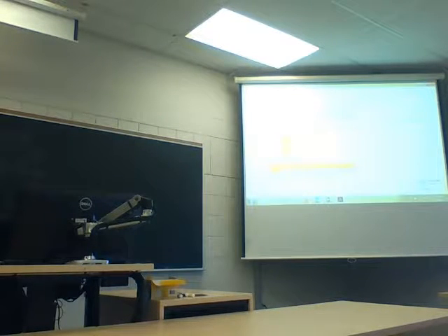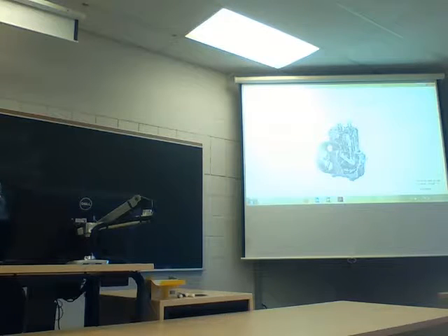Two individual compressors with one driver. The single stage is different. Sorry. A single stage compressor takes place at one end of the cylinder. You were right on with that one. One compression stroke for every crankcase or flywheel revolution. One per revolution. There we are.